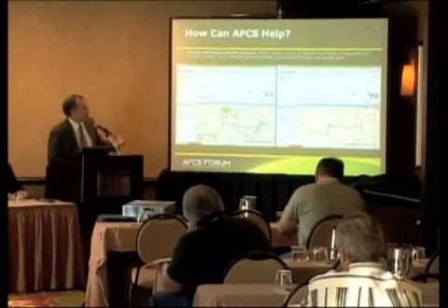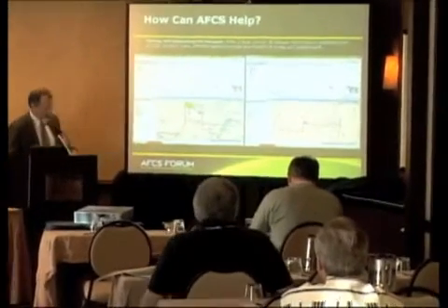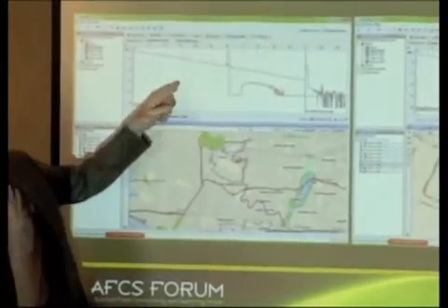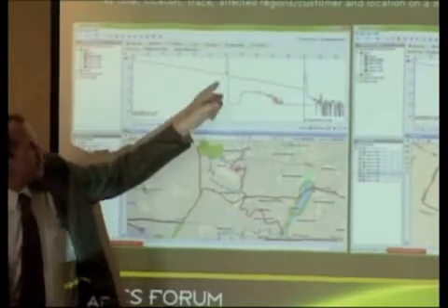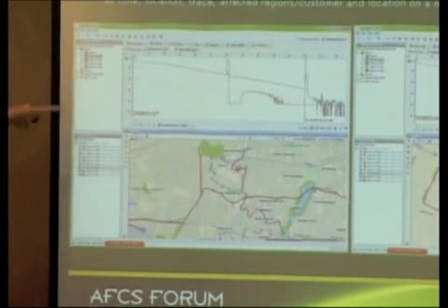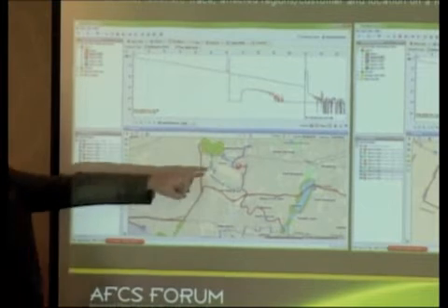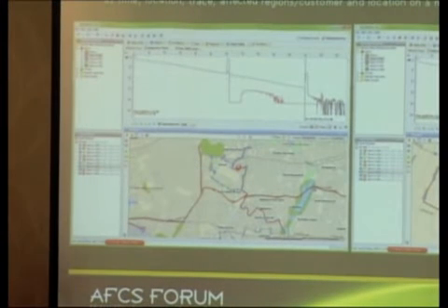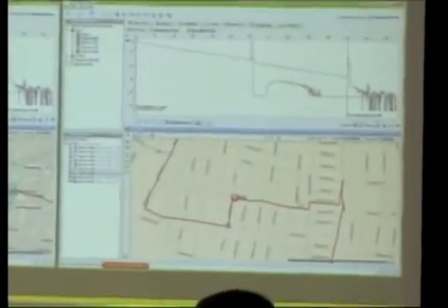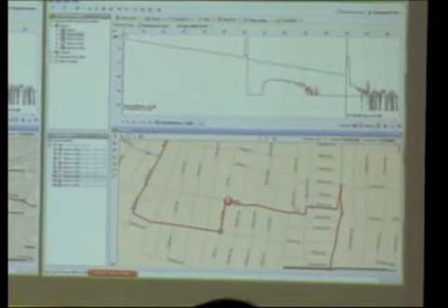Here's how it shows on the map. So again, as I was saying, the test system is continually testing the system. When suddenly there's a break in the fiber, here's your reference trace in black, and then it sends another trace, and there was a fiber cut in this location. So you have a deviation from the reference trace. It then sends the alarm to the appropriate people, and in the menu here, everything is green except for the fiber that's broken, which is now red. The affected fibers below are red as well, and the route shows up in red, and it shows the break on the map. You can zoom in, and you can see the exact location on the street level. And this can also be downloaded or uploaded into Google Earth, so you can see the location in a satellite-type view.